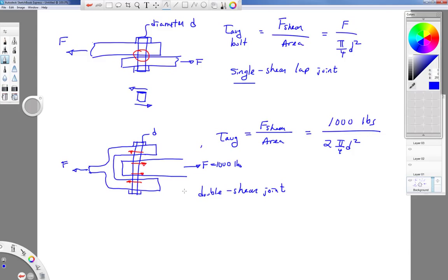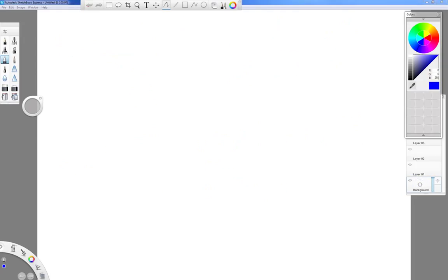Okay, last thing we need to talk about average shearing stress calculations, and we can get into some more advanced topics in shearing stress. And that is what to do if you have a structure like the one I'm going to sketch here, maybe a simple structure like an L bracket or a truss member where you have some force. Maybe there's a wire over here and then a pin support in this location. Draw that pin support like this.